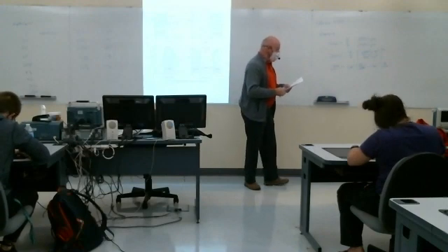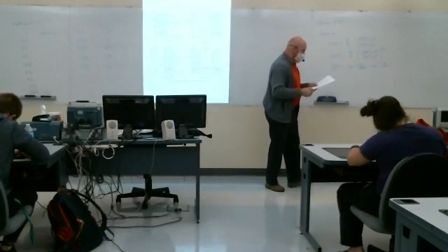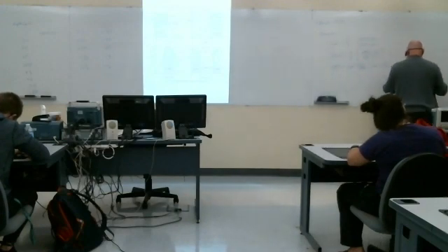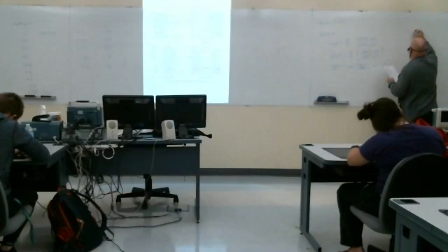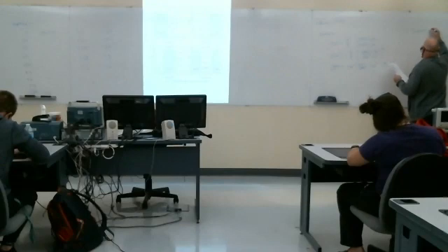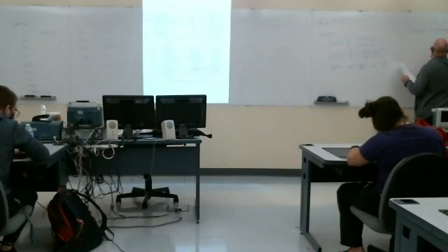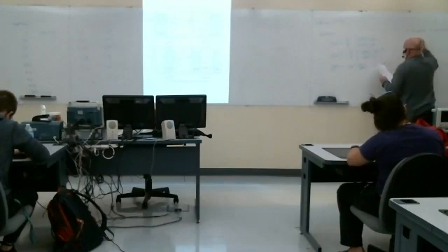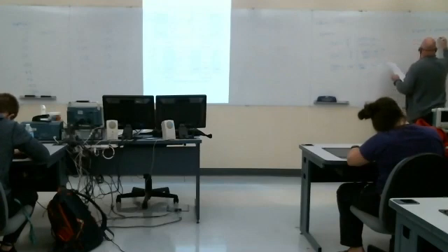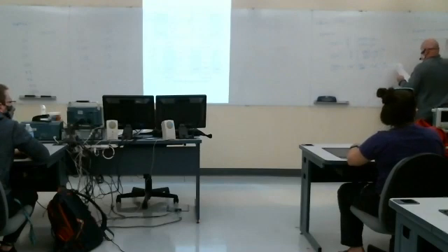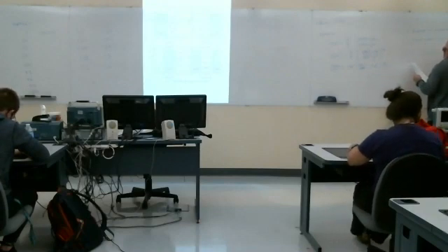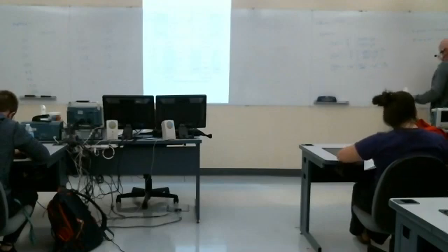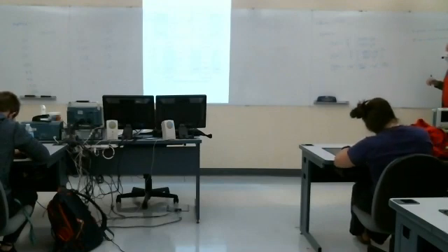on a computer, and we could see what type of filter it is, but we're going to use this Bode method. So the first step is to express the frequency response in standard form. And that means we want to express any first order terms like this, 1 plus j omega over some constant value.